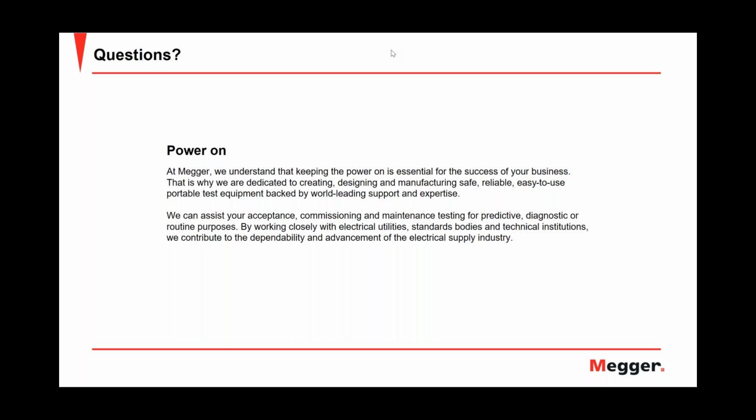And how high do you actually adjust the voltage? Well, first of all, you have your cable rating. You saw Javier's numbers. Let's say we take a 25 kV class cable that typically has an operating voltage of 14.4, but that is RMS, so it's the AC rating. That is associated with roughly 19 kV peak, right? So the cable sees 19 kV at 60 hertz, 120 times every second.